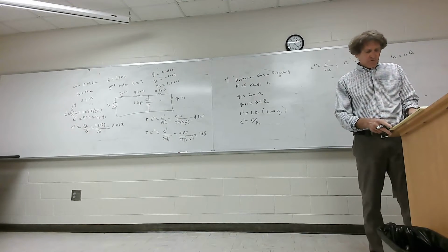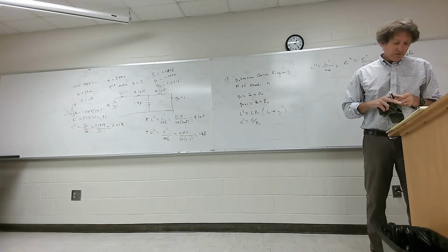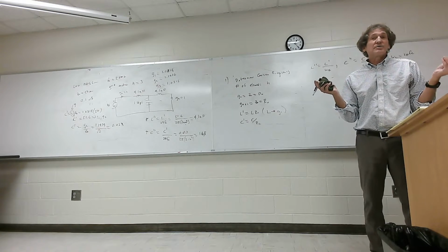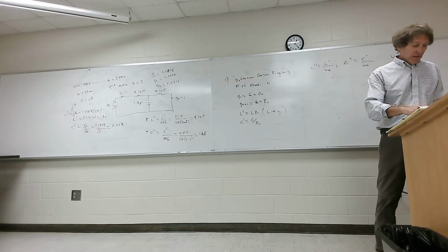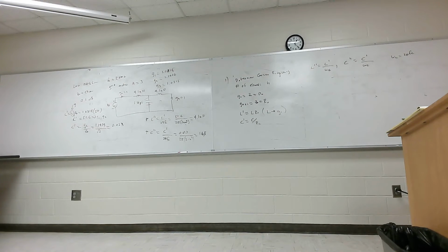And finally, if you want a high pass filter out of this, everything starts with these low pass filter designs. The component values you're going to get are going to be for a low pass filter. When we want to go to high pass, and this is in his book, you're going to have a transform. This is pretty straightforward, but I'll show you what it is. If you look at table 10.4, he'll give you actual values in equations 10.73 and 10.74.